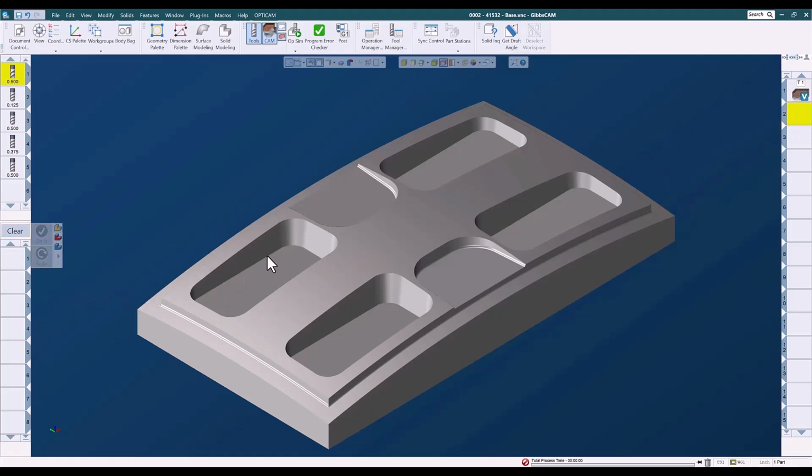I think the next thing I'm going to deal with is going to be the 7.5 degree walls on these 4 pockets. There are a few ways that I could approach that. The main thing that I want is minimal retracts, minimal times the tool pulls off the finished surface. So I want to start cutting this surface or this edge here and finish cutting this edge, but with a spiral down. So my passes are going to be closer together on the short side than on the long side. But let's see what we got.